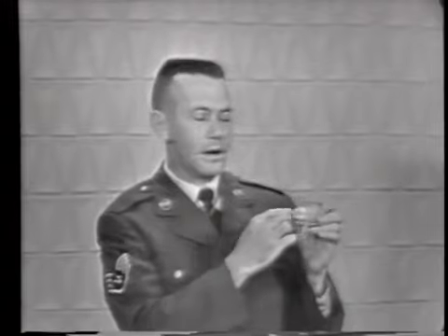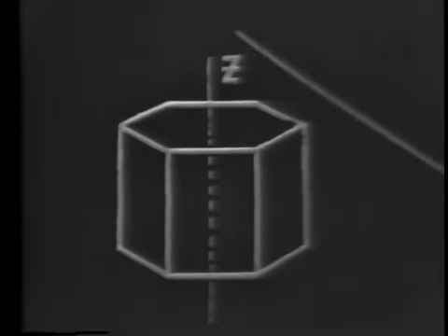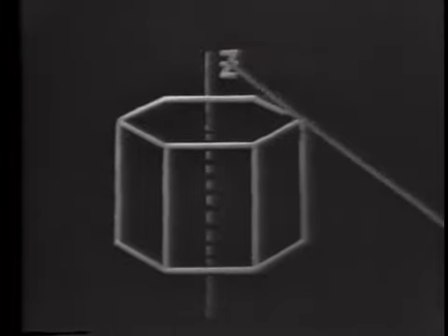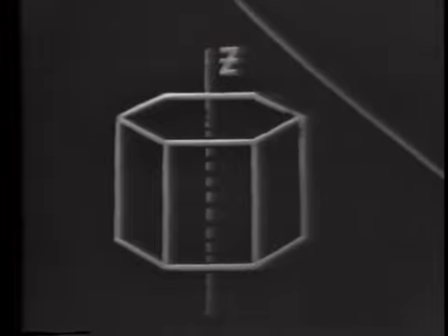When a piece of crystal is going to be cut, imaginary lines are used as the reference points for cutting. These imaginary lines are known as crystal axes. Let's take a look at this drawing of a crystal and see the exact location of the crystal axes. The axis passing from point to point, or end to end, and directly through the crystal is known as the z-axis. Remember, from end to end, directly through the center.